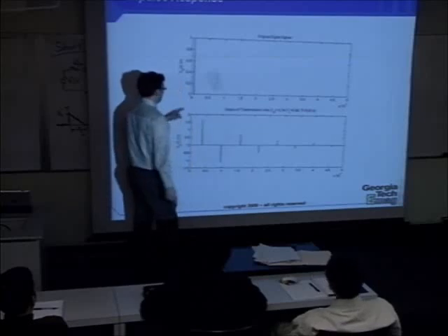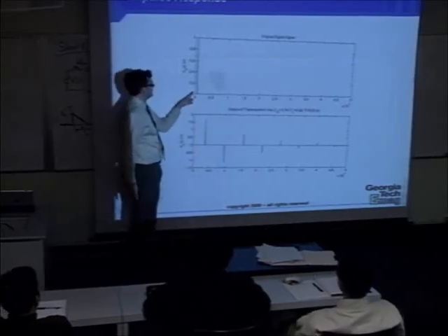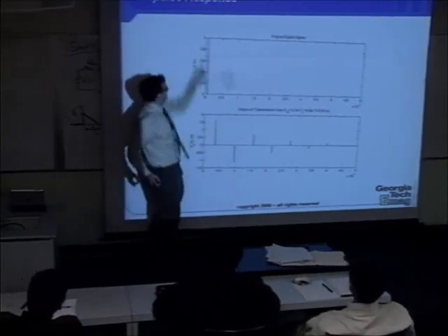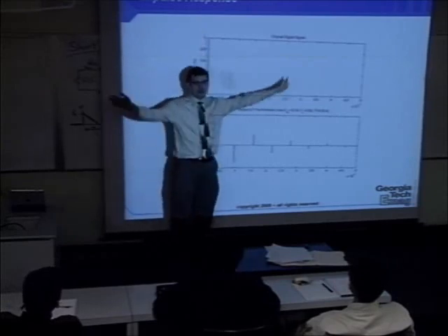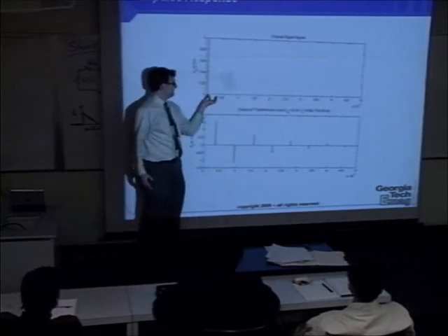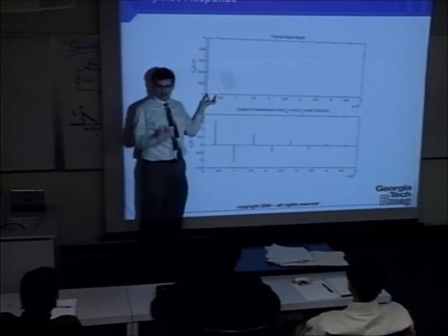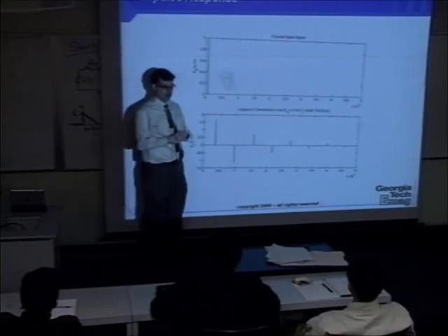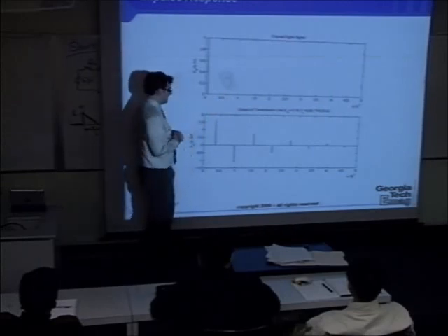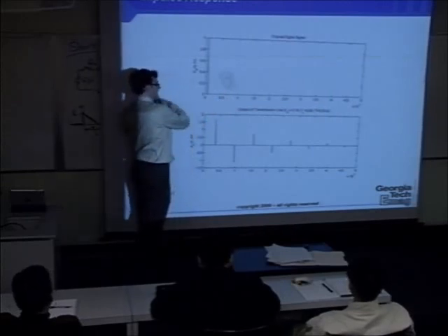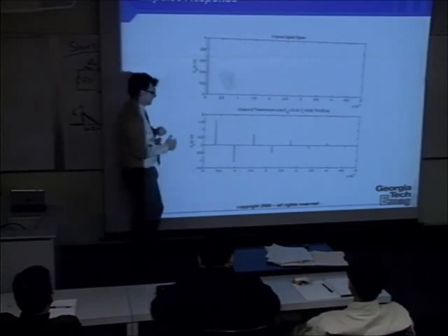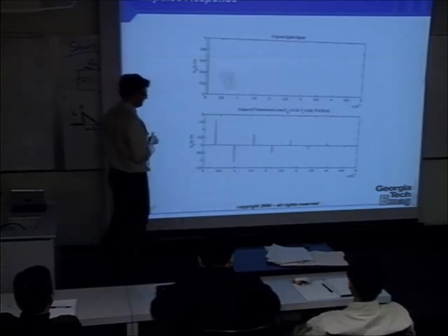So here's the graph of that, the input. 0 everywhere, infinite at 0, and infinite in such a way that if you integrated across it, you would get a unit value of 1. That's the mathematical definition of a Dirac impulse. If you integrate it from minus infinity to t, you get the unit step function. So it's really the derivative of the unit step function.